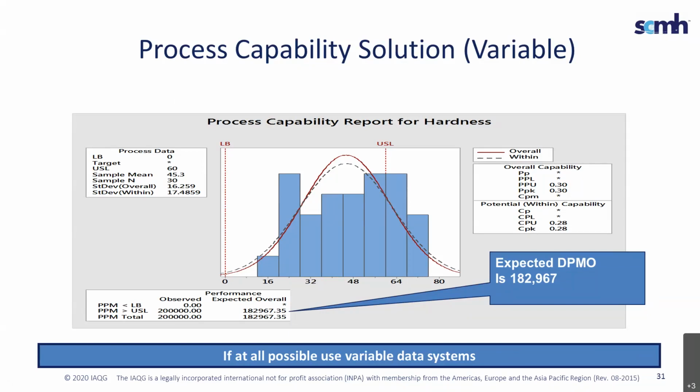This next one is sort of very similar. You might have covered it, but when doing a PPAP, process capability is a key element. How do you handle this when the quantities are very small and it may take a year to get enough data to do process capability?